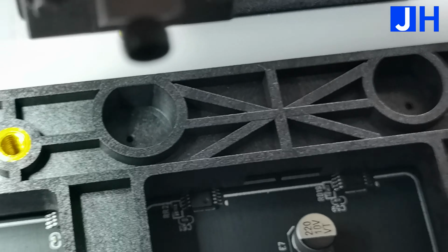Before assembling the screws, we first set the servo configuration parameters and adjust the torque to the minimum of 30. Set the tightening torque of the screws to 30, then click OK. Next, we assembled the screws.